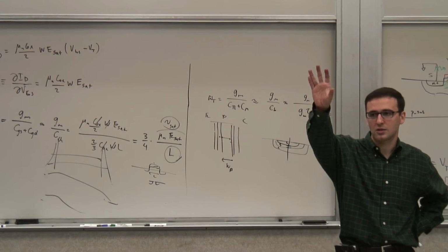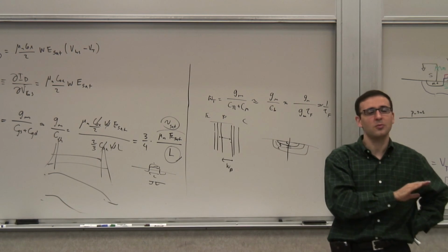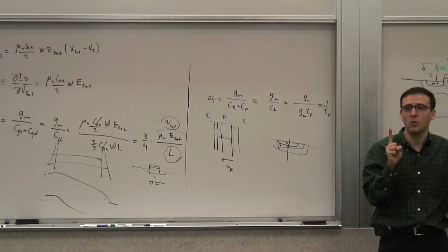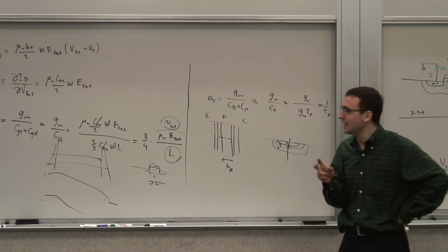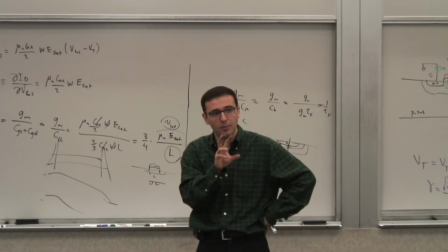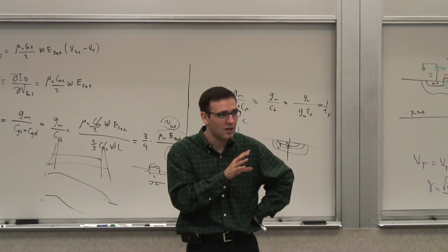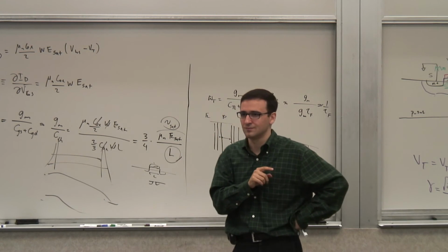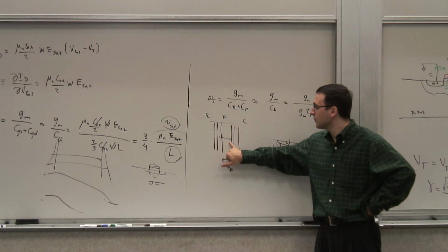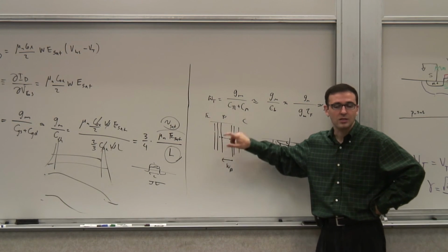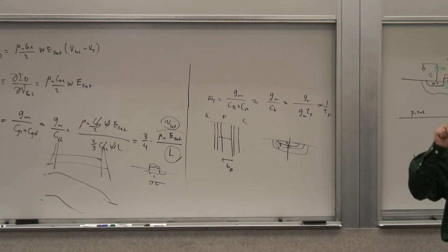Nowadays, any microprocessor you pick, anything in your cell phone, anything in your computer, it's almost exclusively MOSFET because, number one, you don't have DC power consumption in the MOSFET gate. And number two, if you make a bipolar gate that does not have a large DC consumption, that gate will be very slow. That really goes back to the fact that bipolars are minority carrier devices. Because the way to do that is to saturate the transistor. Put the bipolar transistor in saturation.